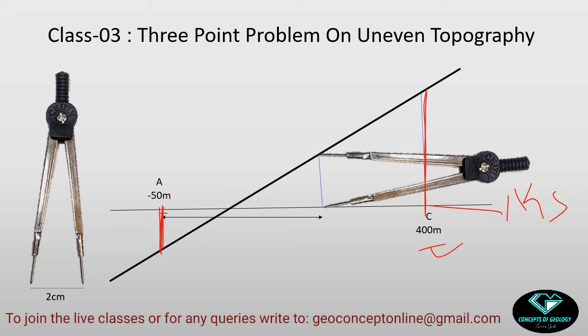Now I have a third borehole, the B borehole, which has an RL value of the coal seam of positive 200 meter. So in between point A and point C, I will have that value somewhere. To find the borehole, I need to draw a horizontal line of 2 centimeter. Why? Because according to my map scale, 2 centimeter is equal to 200 meter. So I have drawn the 2 centimeter horizontal line. I will take the divider, copy the line, and try to fit this divider in this construction by hit and trial method. Suppose the divider is exactly fitted here. That means this point is where I will get the borehole B.